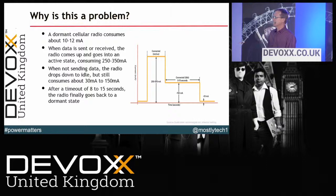When it's not sending data, the radio drops down to an idle state, but it's still using a significant amount of power in that state, and it remains there for 8 to 15 seconds. That's what's called the cellular long tail. And then, of course, finally it drops back down.